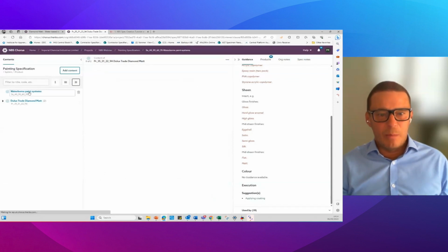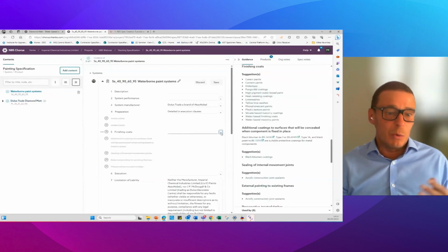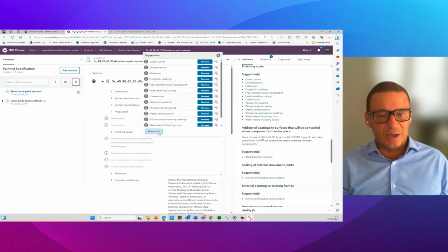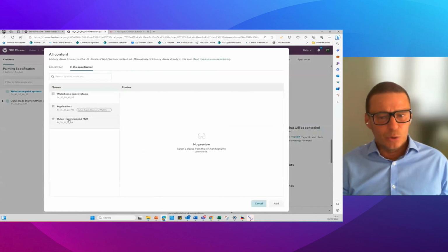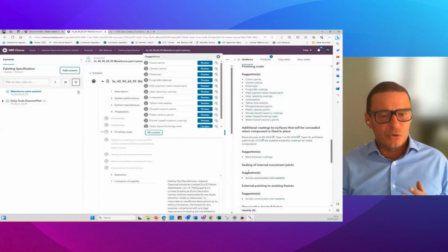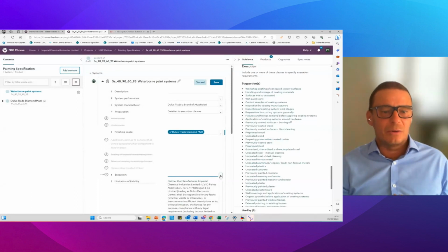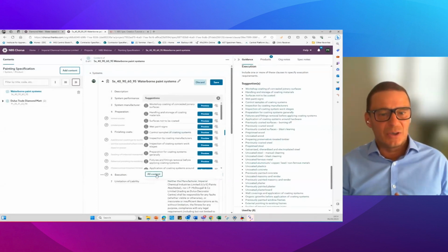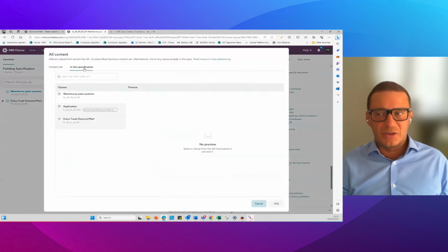And then we will go back to adding in the correct finishing system to the spec. And at this time, we will also add in some additional clauses around things such as correct handling, paint signs, and British standard references to also ensure that the applier uses the correct process. Again, for ourselves, it's all about best practice. And we add these to all specifications we write for specifiers in MBS.